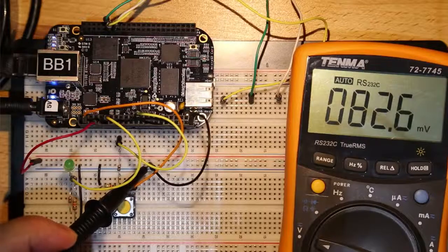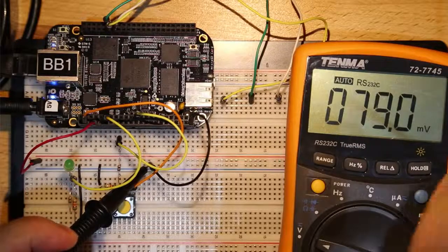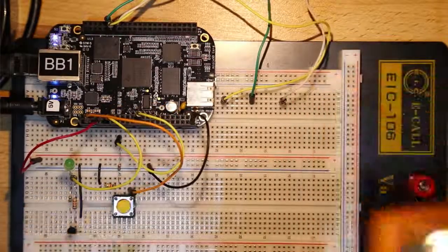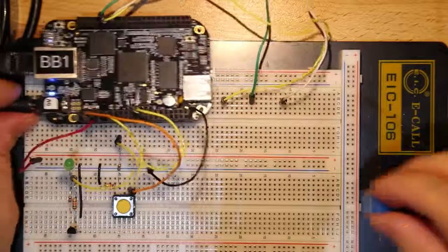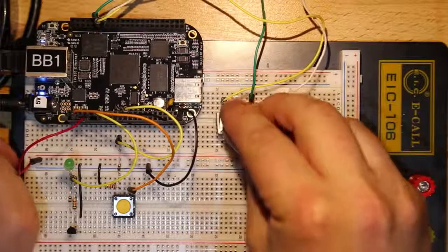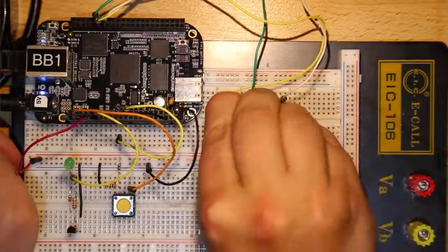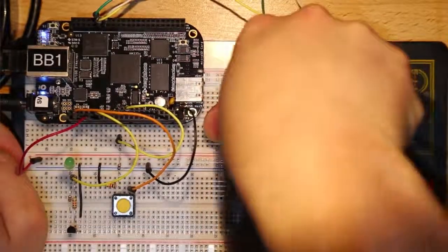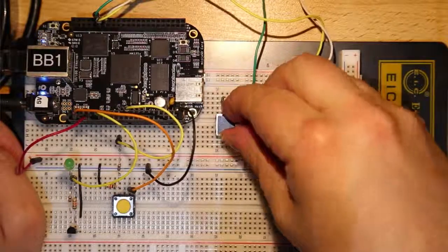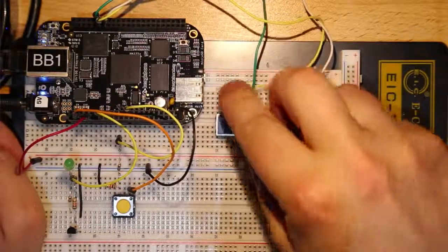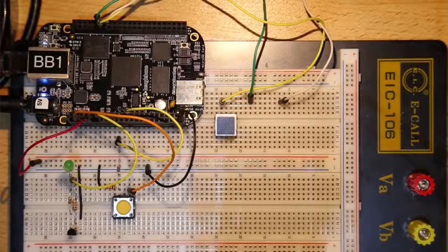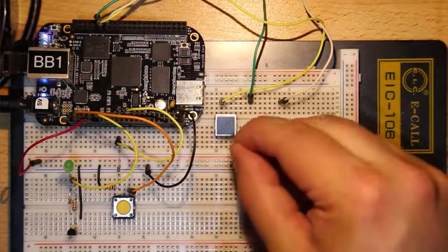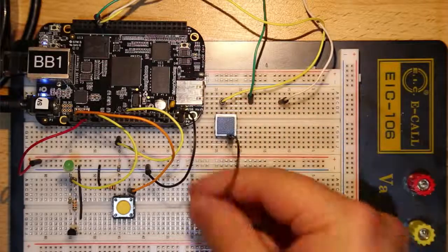So again, yellow, which is in pull-up, has a value of around 3.3 volts. So if we wanted to connect this as a switch, it's very easy. We can use the blue button here. So push it in, and now it's home. It's in pull-up configuration, so we're going to ground the other side of this pin to our ground out.